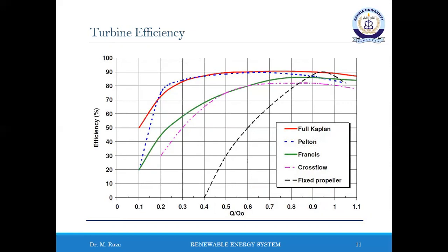According to the efficiency shown in this figure, it is practical to determine minimum admissible flow condition as a percentage of the design flow. For Pelton turbine, 10 to 20% of design flow, depending on the number of nozzles, is the minimum admissible flow condition. Similarly, Francis turbine has 40% of design flow, and Kaplan turbine has minimum admissible flow condition about 20 to 40% of design flow, depending on the double regulated or semi-regulated system.